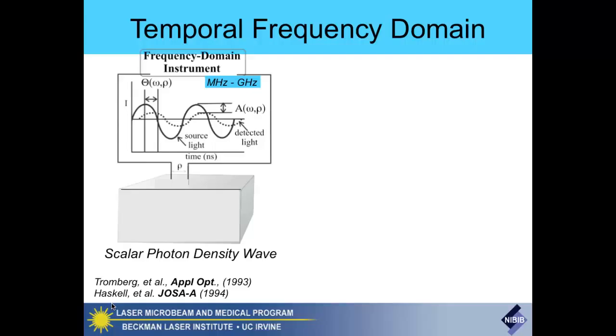Now, if you just get right above that threshold, so you're just lasing, and then you hit it with RF, so now you're swinging the current very fast in time, you will get the light output to follow the current. So that's the trick with modulating laser diodes.